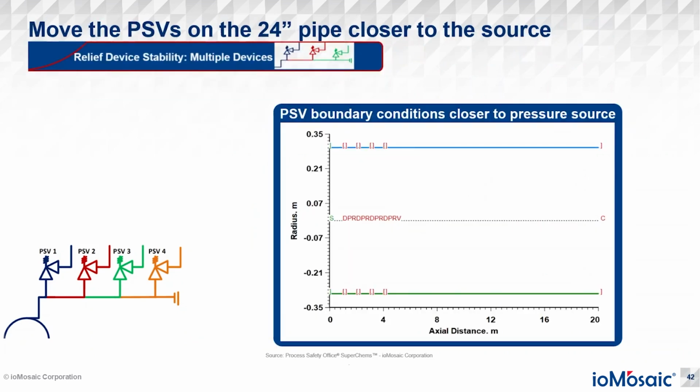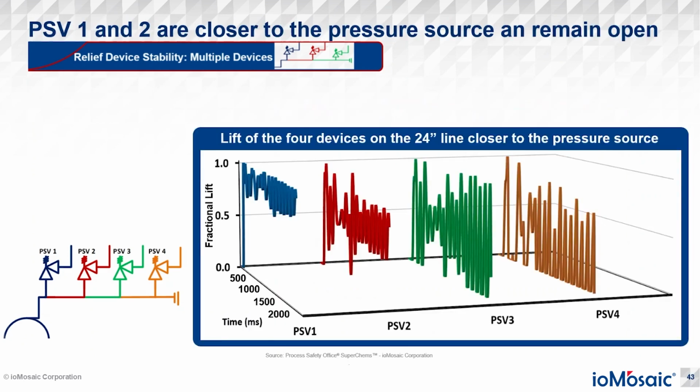So then, I've gone from keeping them quite close to the closed boundary, to having them quite spaced out, and then just for completeness, I pushed them all over to the source. And again, we can see a very interesting result. PSV1 flutters quite a lot. PSV2 again flutters quite a lot. PSV3 does chatter, flutter, then goes back to chatter again. And then PSV4 just flat out chatters.